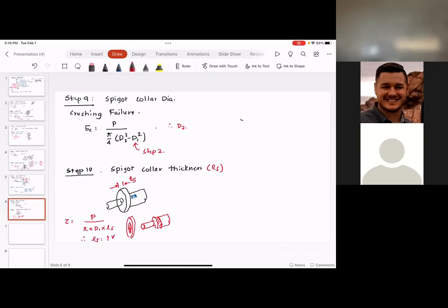There is one more step, that is we have to check cotter for bending. And that step is a little bit involved. And many a times when you do this step, you would notice that cotter actually fails in bending. Now I want to emphasize, and before I do that, let me quickly go to the steps.